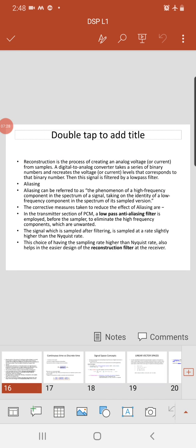Two very simple interpolation functions are zero order hold and linear interpolation. With zero order hold, each sample value is represented as a rectangular pulse of width Ts and height y[n]. With linear interpolation, the continuous waveform values between sample values are obtained by connecting them with a line. But both these cases introduce errors, so we have to use a better method. A complete sampling and reconstruction system requires both C to D and D to C converters.